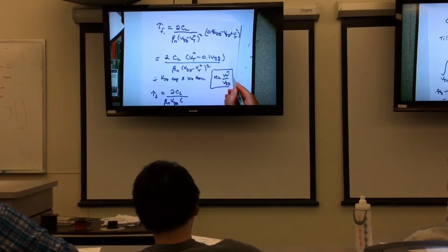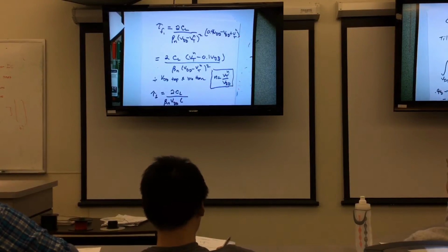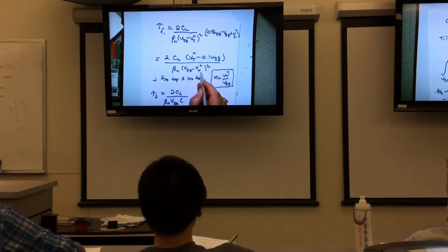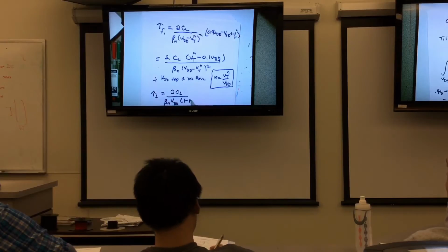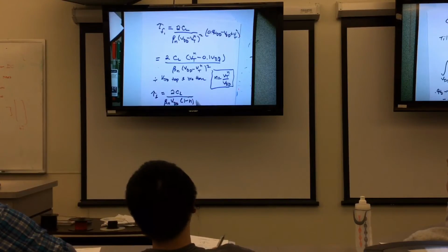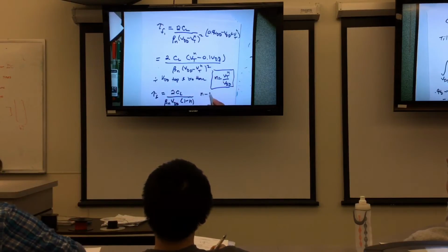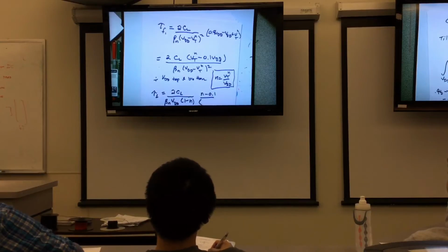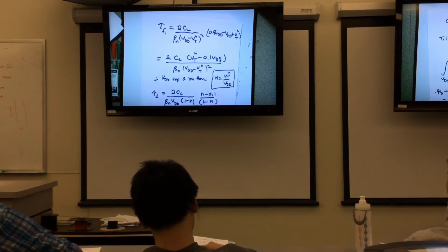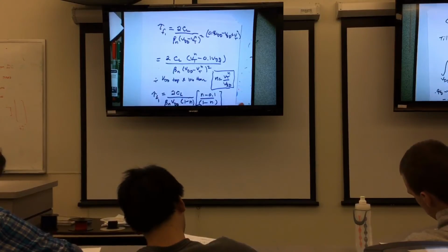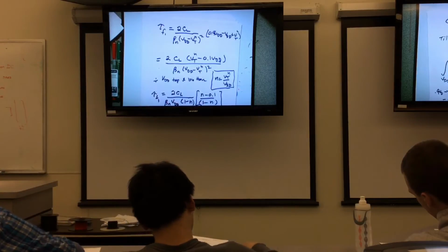I'm just going to define that parameter: the ratio of the threshold voltage to the supply voltage. If I do that and divide by VDD over here, I'm going to get 1 minus n squared. I put 1 in here, and then there'll be 1 up in here. This is going to be n minus 0.1, and I'll divide by the other one over here, 1 minus n. The reason for grouping it that way is we've only just analyzed TF1, the first part of it. There'll be another piece for the other segment, but I'll share some things already that you can see in common with this.